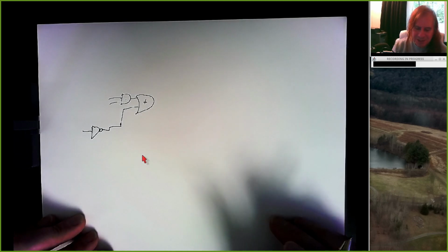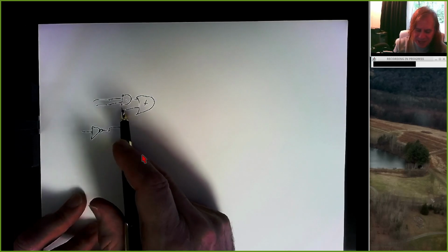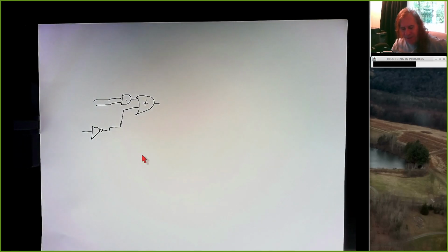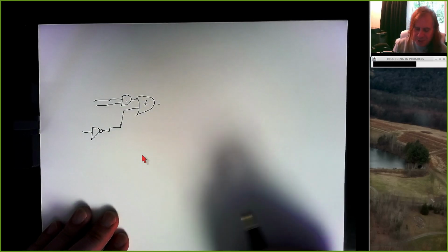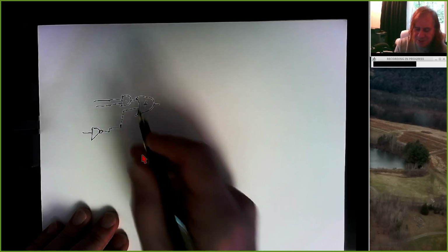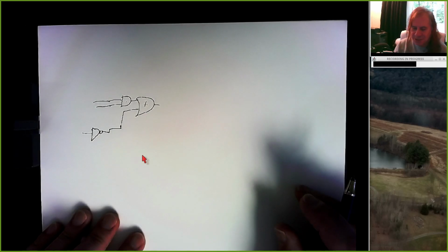So it's got to have logic symbols. And these are our standardized symbols. This is an AND gate. This is an OR gate. This is an inverter. And don't draw pictures of the chips with the pins on the side and connect to the pins, because that doesn't tell somebody looking at it what the logic function is, right? So you want to use these symbols, but we want to know, how are you going to create a circuit with these 2 inputs going into an AND gate and the output of that going into an OR gate, and so on. So we have to add something to our circuit diagram.